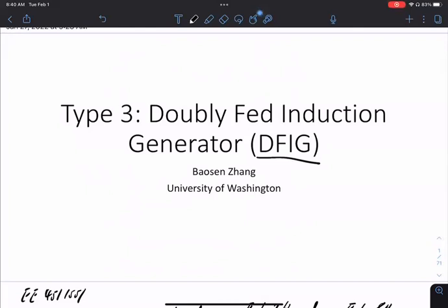And basically where that comes from is you have a rotor circuit. You have a voltage injection at the rotor. Right? Sorry? You're adding some sort of excitation system, yes. No, except the excitation comes directly from the grid. So it's not like a synchronous generator where you have an external excitation system. This excitation comes by drawing another wire from the grid. So it's not a standalone excitation system, right?